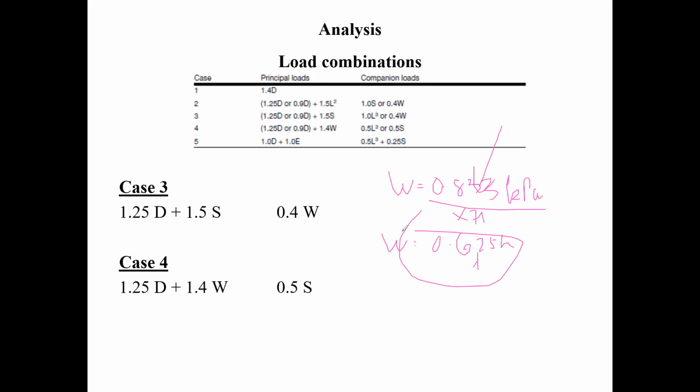You calculate all the wind pressures on the external one, you calculate all the internal pressures on the internal one, you check which side has the highest one, and you design the stud for that. And that's how it's actually done.